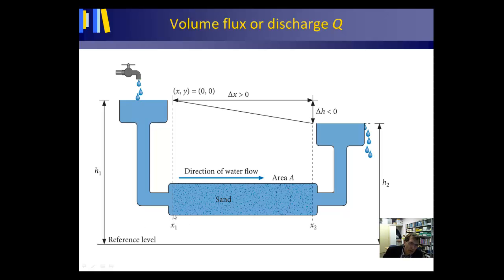Well, if we were to look at this screen and establish the hydraulic head here, for instance in the mid part here, this would be your elevation head, and of course this part would be your pressure head. And then elevation head plus pressure head gives you hydraulic head. Well, everywhere along this screen, whether I'm looking here or here or here or here, the hydraulic head is the same. So I have a fixed hydraulic head of H1 here. Similarly, I have a fixed hydraulic head, but a lower hydraulic head, H2 here. So water is flowing from left to right through this system.